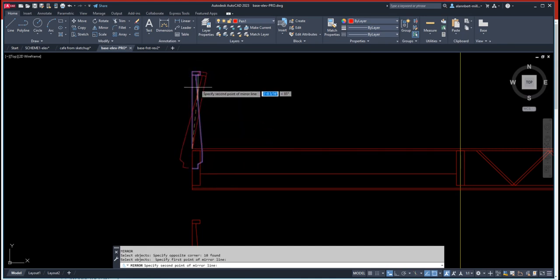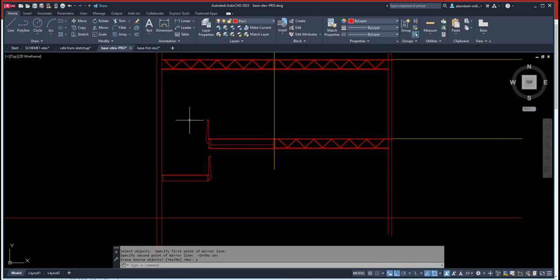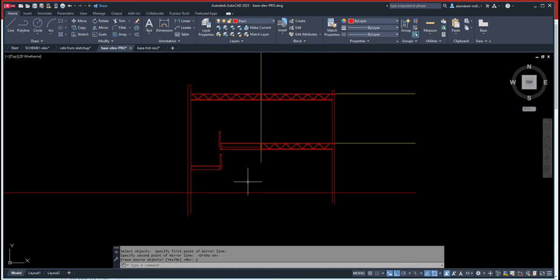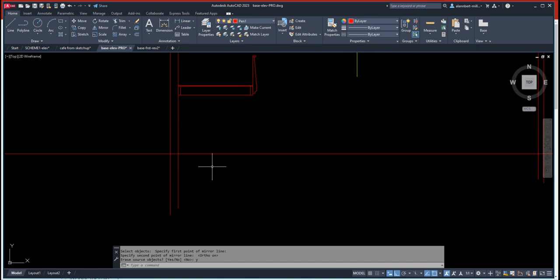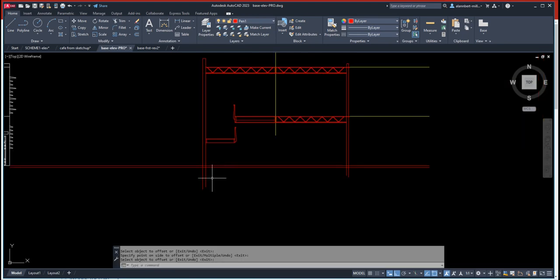from here, going all the way. I hate my keyboard, but anyway, there's no shortcuts. And yes, there you go. So that prevents people from falling over. This one prevents you from falling and sliding here. Anyway, that's what it's gonna look like. Okay, and now let's do the bottoms. On the bottom, there's a slab, and the slab would be dictated by your engineer. Let's say 6 inches downwards over there.